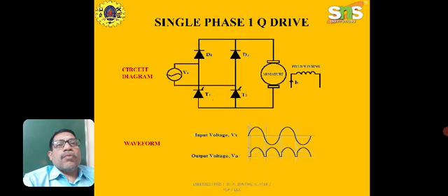The circuit diagram for one quadrant may be two diodes and two thyristors. The input supply AC is Vs, and the output voltage DC is given to the armature. Here it is an armature voltage controlled method, because the DC supply is a controlled one which is given to the armature in order to vary the speed. Whereas here the field winding is independent, where the DC supply is given with the help of an uncontrolled rectifier if AC supply is available in that area.